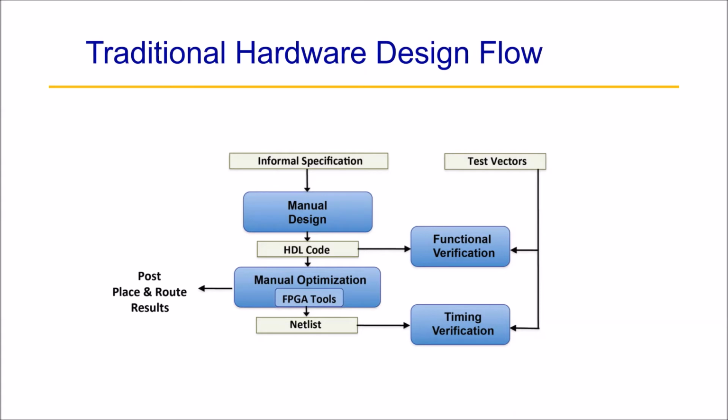The netlist is the output of synthesis process. At this stage, we can verify the timing of design. If it passes the timing verification, we can port the design to the FPGA board.